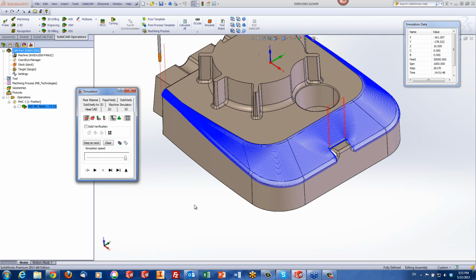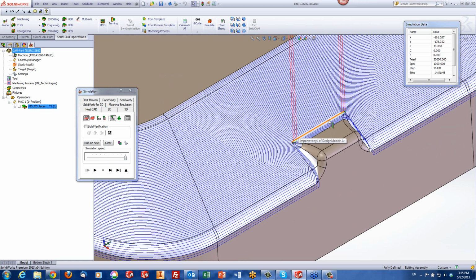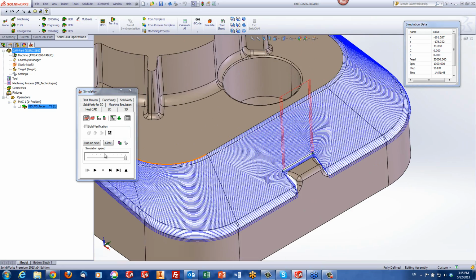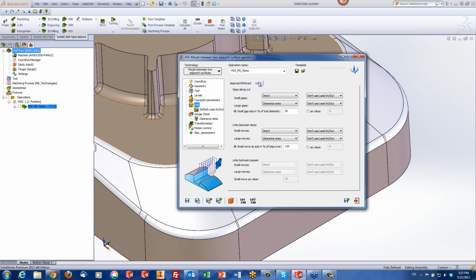Now, one more thing I'd like to deal with is that sometimes you have areas of surfaces where they're not completely touching exactly the way they are. So there are gaps in the toolpath, or the toolpaths are too close to one another for whatever reason. So in this case, I'll just go back. And since we're talking about our gaps, I'll go into link.